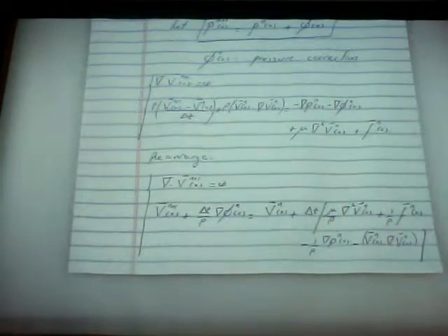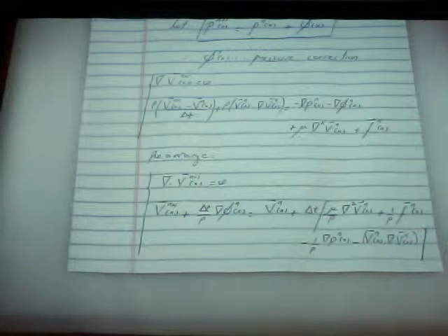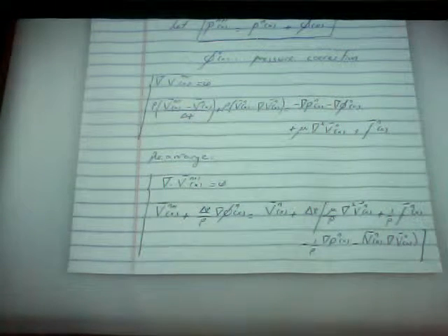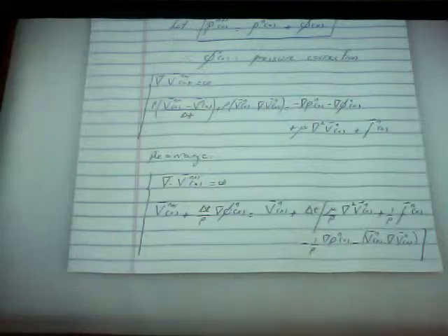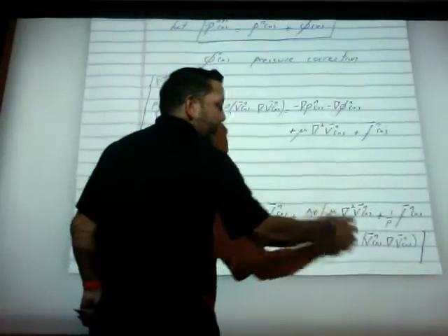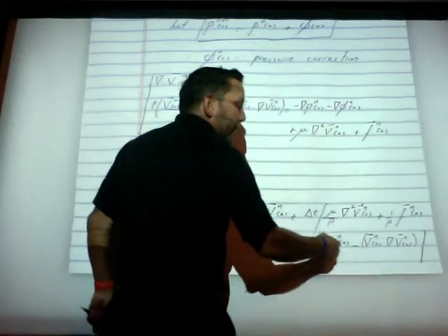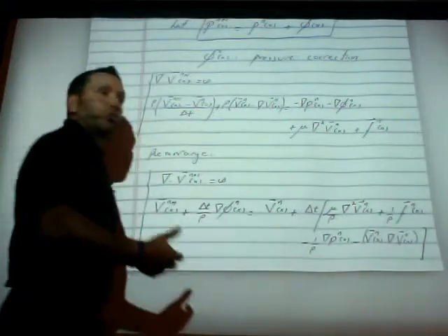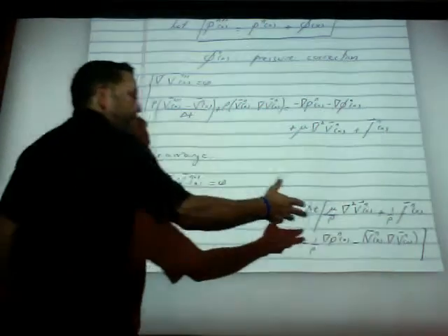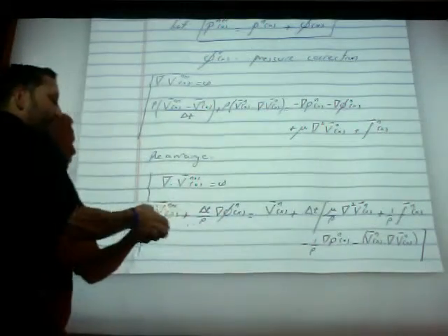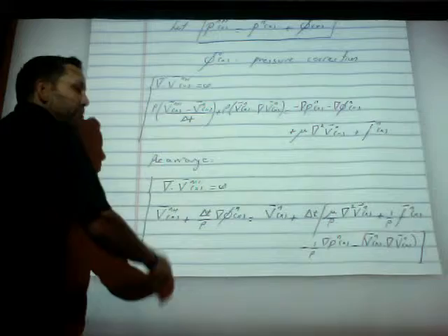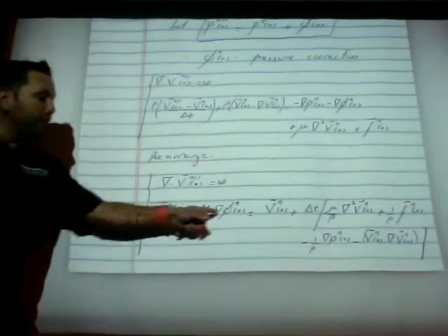At time step n, we know everything currently. So we can advance in time. So if we take the previous velocity and the previous pressure, which we know, get the Laplace, get the gradient, get the Lagrange derivative, which we know how to calculate using meshless methods, add this up, and then we have this, whatever this is.